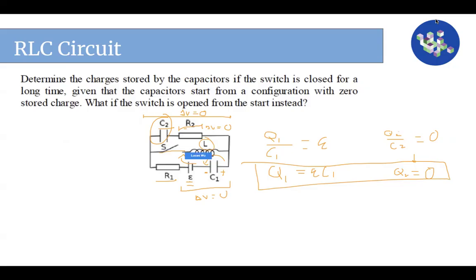Remember, we have the voltage drop across an inductor, let's say V inductor, VL, that will equal L, your inductance, times di/dt, I dot. Because we are assuming it's a steady state, we'll say that I dot is equal to zero, so that means VL is just equal to zero.